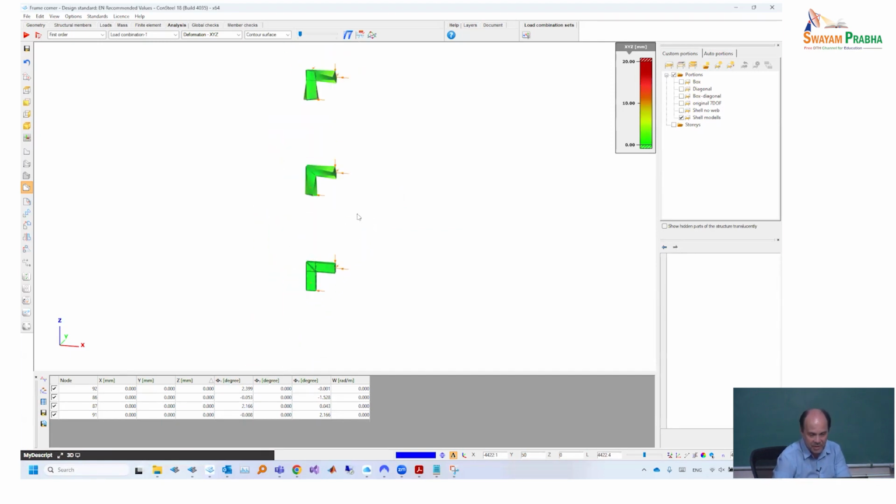So what we did in Consteel is that, of course, we are using beam elements, and it is possible in Consteel to make models with complex modelization. It's possible to use beam elements, and for the corner use shell elements. We have constraints to consider the connected elements, including also the warping deformation. So everything is possible to do nicely, but it is slow and time-consuming to model a big structure like that. So we were looking for something maybe less precise, but a quick and practically easy to use solution.